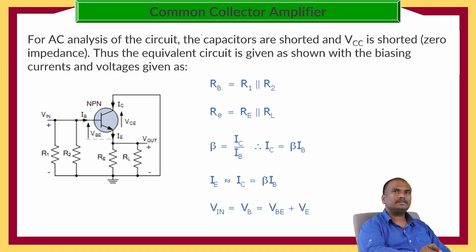For AC analysis of the circuit, capacitors are shorted and VCC is shorted.